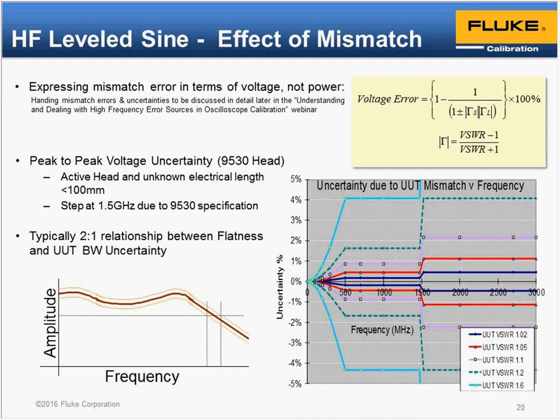Now, this is the oscilloscope, and it has its input characteristics, and as designers of a calibrator, we have no influence on that. As metrologists hooking up the two items, the best thing we can do in practice is to make the source impedance, the source match of the source within the calibrator, as good as possible in order to minimize the uncertainty in the peak-to-peak voltage. And that's what we see on that chart down at the bottom of that slide.